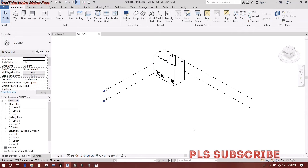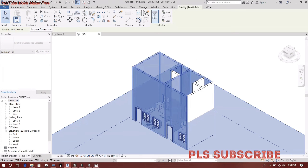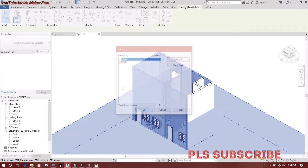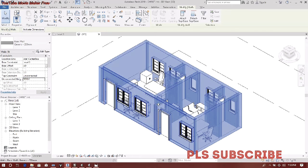So we'll go to 3D. I have these floor plans already. All I need to do is filter that, then I'll have all my walls. Press SA to select similar. Change the height of my building to 3000. Yep, so we have that.